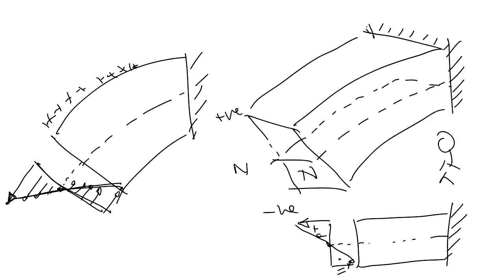Yes, doctor. Okay, so now guys, as I mentioned, we physically were able to represent this stress distribution and show the variation in the stresses from positive to negative. And we found that, practically speaking, if we need to move from positive to negative, I have to pass by a layer which is neutral, neither subjected to tension nor subjected to compression. So now I need to prove this also through the formula. The formula tells me that sigma bending is equal to M times y divided by I. Okay, M, we are assuming, guys, that our M is constant.